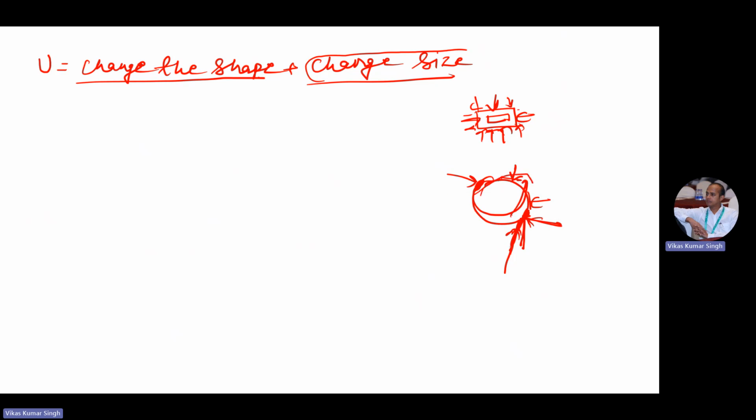Whenever any component of the force is in the shear direction, the material shape will not be consistent, the shape will change. Otherwise, if this P is always perpendicular to the tangent of this sphere, only size will change. Either it will shrink or expand. Expand means if it is pulling. So distortion in the material is coming only because of shear. Only because of shear. Okay? Means distortion.